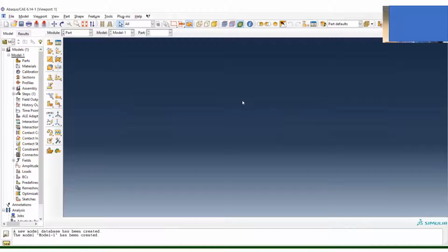So this plate we have is a very thin plate. We assume it has a plane stress condition. I need to tell you guys that Abaqus does not have its own units, and so that means the modelers, the researchers, must be very, very careful.